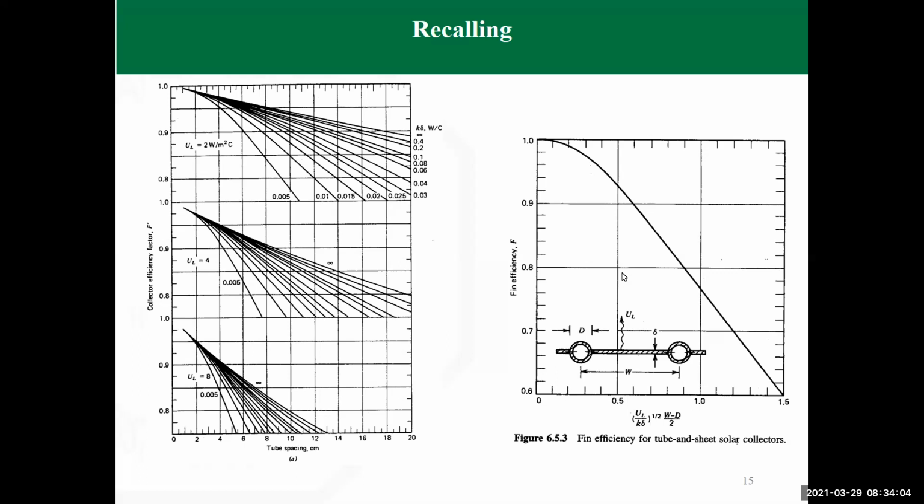The energy falls onto the absorbing plates, and the plate has a temperature distribution with a higher value in the middle, midway between the two pipes. Then the temperature reduces until it reaches the pipe, which is our heat sink, where the energy is being absorbed.